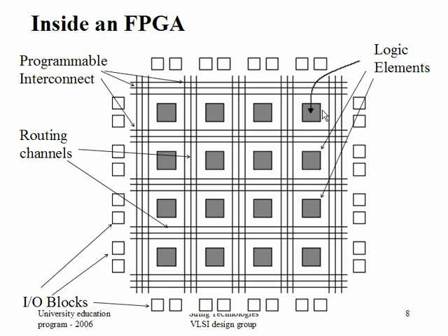See, simple. The point is, when I say routing channel, it is a wire running through. When I say programmable interconnect, it is some matrix where you are connecting those wires with some switches. We did not discuss it in that way yesterday. Yesterday we just said programmable interconnects. A programmable interconnect is basically a kind of matrix where I have many MOSFET-like elements, where I can program those connections. Routing channel means the wires which are running between the various blocks. So routing channels are just wires. That's all.